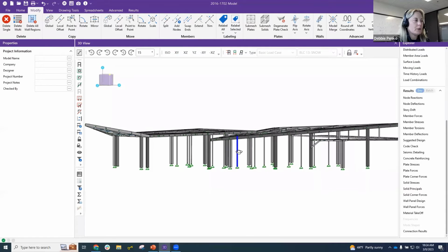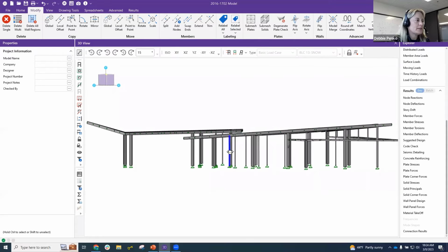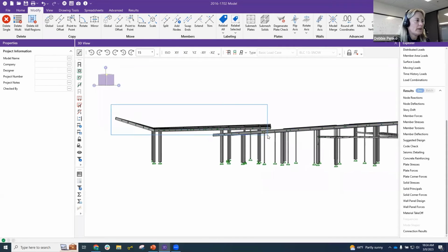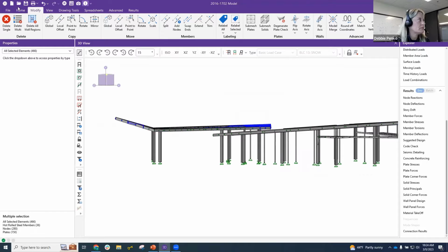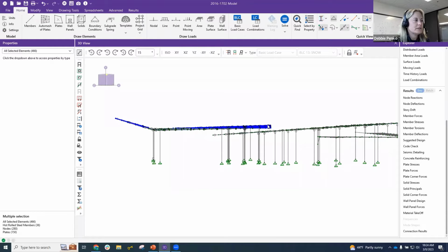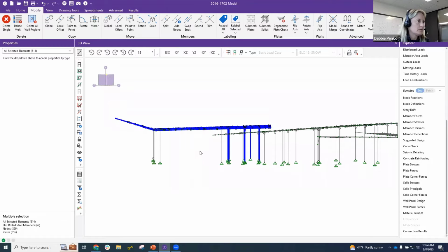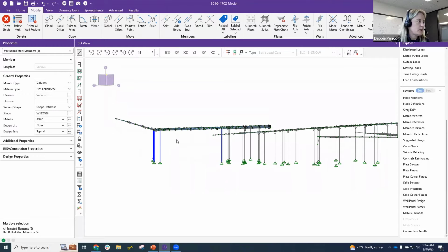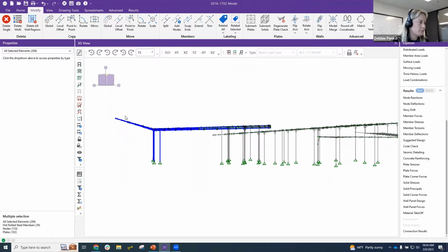The lock button helps to lock out the entire model. The way I could do that is I can use my mouse, and I'm going to go off a render so it's easier to see. So I grab all of the things here in my model, and I'll grab these pieces as well. It's replacive. If I use my control button, it will actually be additive in that selection. So you can see how I'm doing that. As I use my control button, I'm grabbing more and more selection.